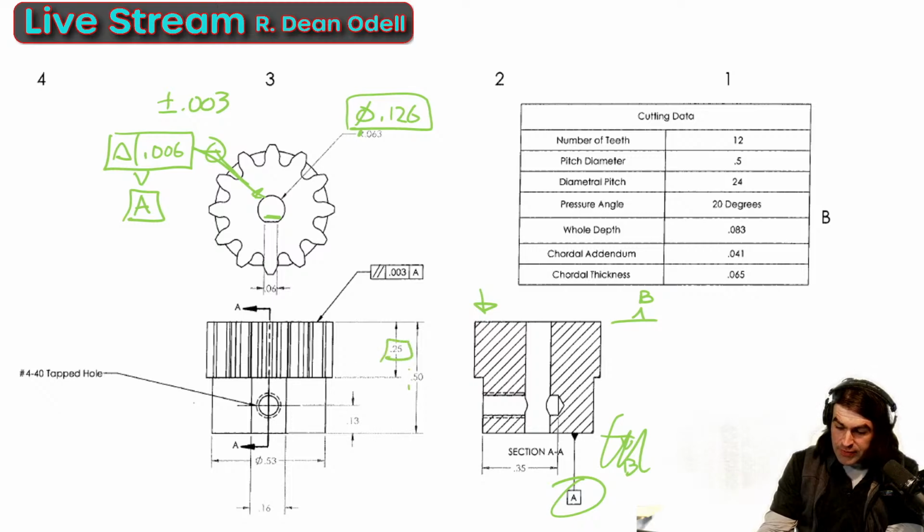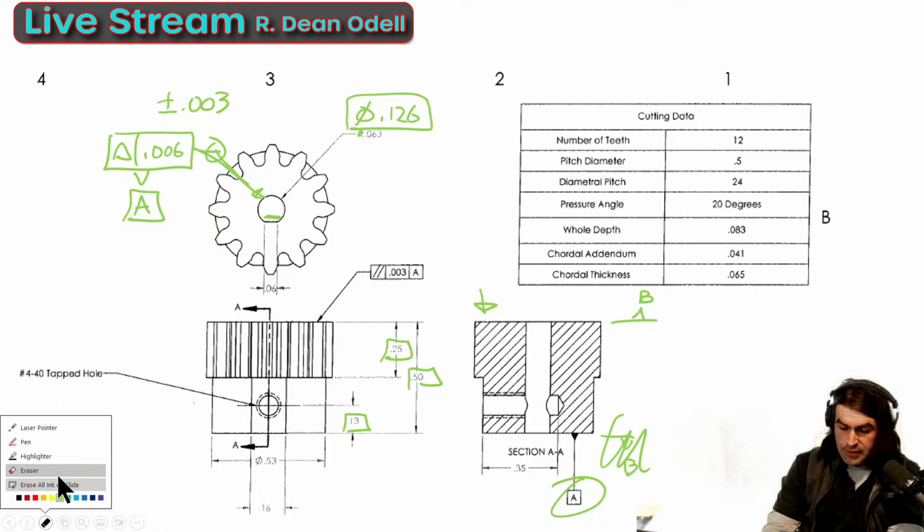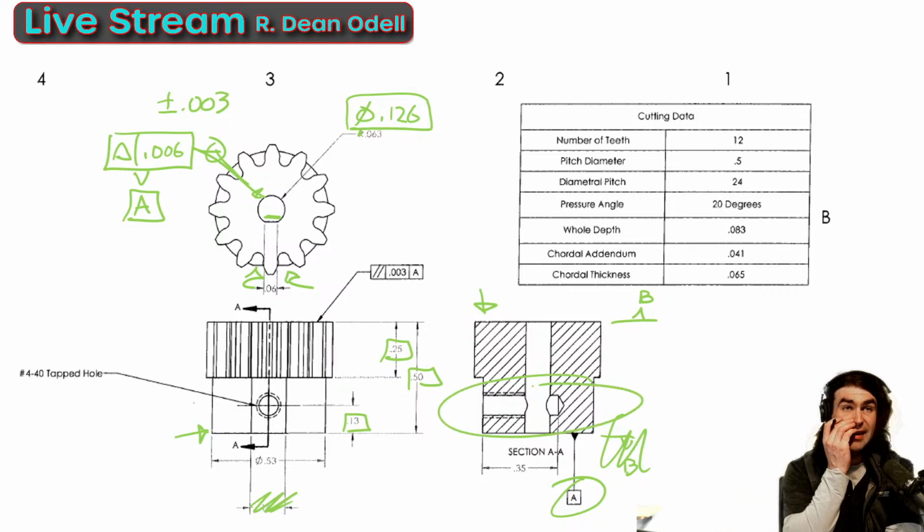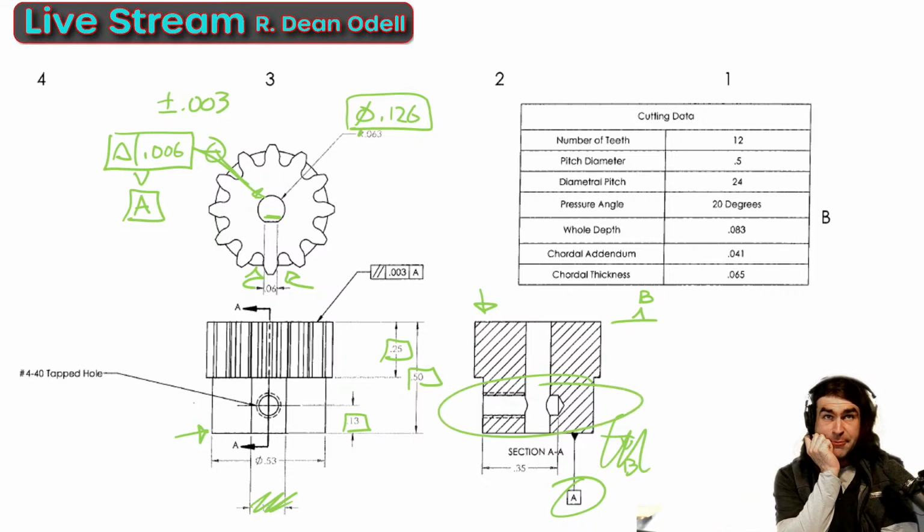Okay, so we would go basic, basic, basic. This diameter here, because it has a flat, we'd actually probably go, well, I don't know, let's not go basic on that one. I want to talk about something else. This flat, again, like I said, I wouldn't dimension it like that. We really need another view to show what I'm talking about is this feature. It's kind of barely visible on the back side and here. We really want another view for that.